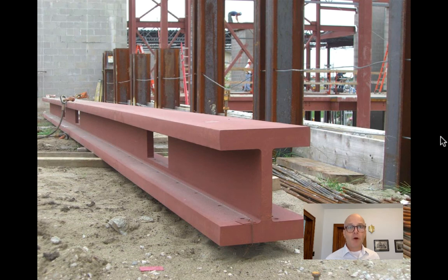This also, I hope, explains why when we're dealing in bending, we see shapes like this all the time. The W shape or the I-beam is basically the mathematics of cross-sectional shapes, the mathematics of deriving section modulus in steel or in concrete or in whatever other material you're doing this in. You will almost always find that beams want to have flanges, usually symmetrically placed, and a relatively thin web, so that most of that beam's cross-section is pushed out to the very, very edges where it's doing the most work.